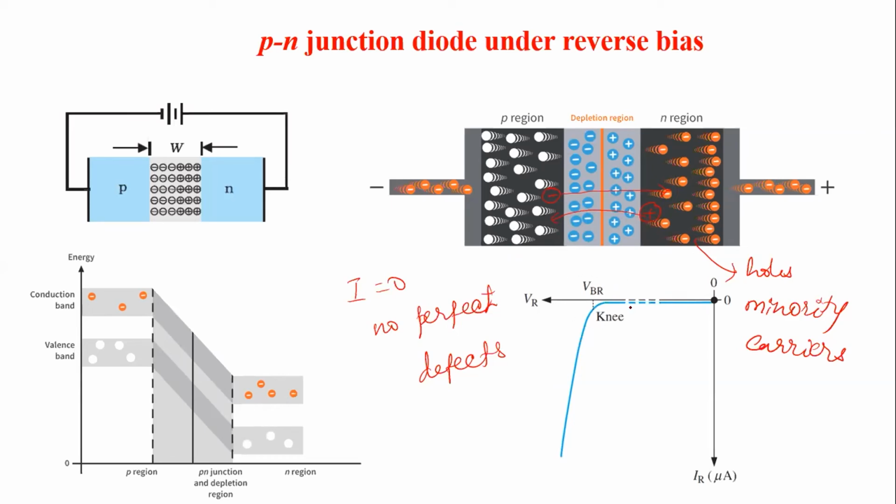When you further increase the voltage, the carriers that are moving due to this potential develop a high kinetic energy. Once a high kinetic energy is developed, they start to disturb the lattice and collide, not physically but through electrostatic force, with the other electrons present in the lattice.